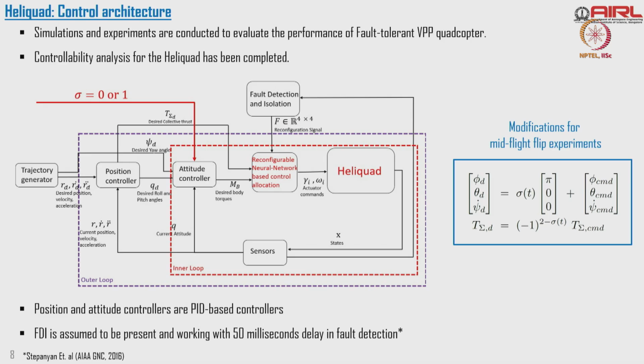I can't do that here because for every thrust I can get two values of RPM versus pitch. So I have to approximate this inverse relationship between the torque versus RPM and pitch. Blade pitch, when I say pitch here, I mean the pitch of the blade, not the drone's pitch angle. It is the pitch of the blade I can control here. So I have to do this.